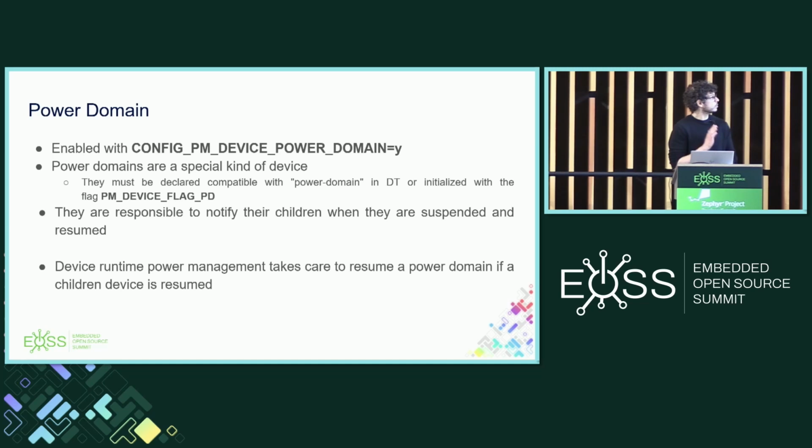Okay, so finally, power domains. A power domain is an abstraction to group a set of devices that are powered by a common source. On Zephyr, support for power domains is enabled with the PM device power domain option, and they are implemented just as regular devices. What basically makes a device a power domain is its relationship with other devices. This dependence can be defined in device tree or can be done dynamically as well.